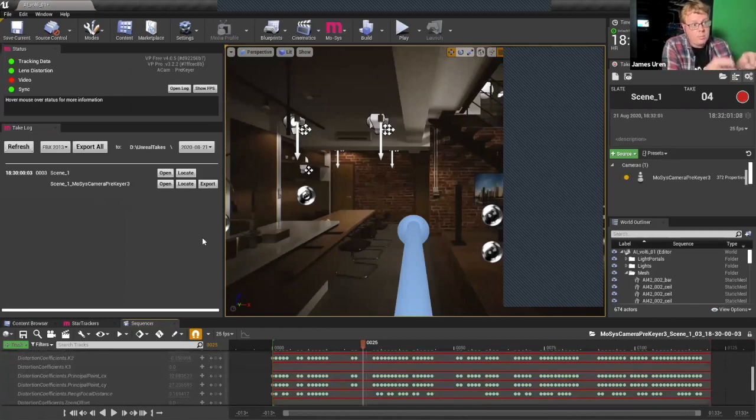And you can also turn up all the dials now. You can turn up your ray tracing and all that stuff because you're after the fact. You don't need to be real time anymore. And you can then take the plate that you recorded in camera, so the green plate, and just do a 2D composite over the Unreal rendered plate. So there's a 3D compositing and a 2D compositing workflow that's supported by this.